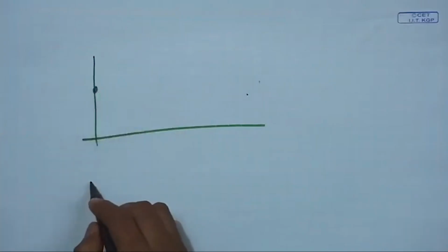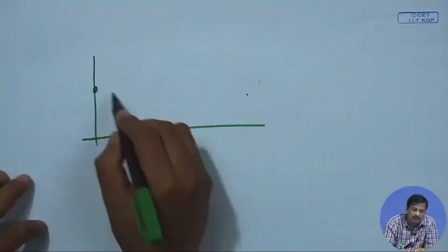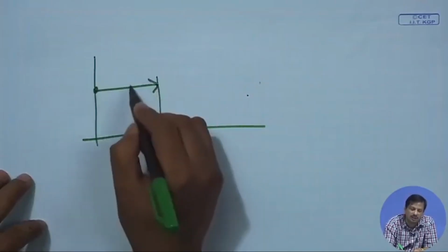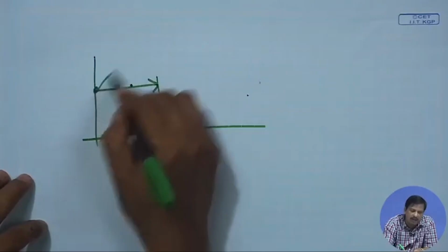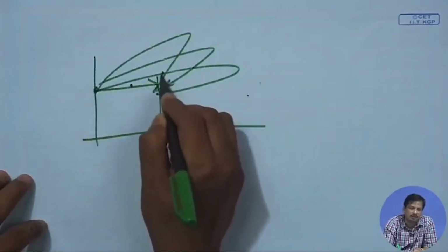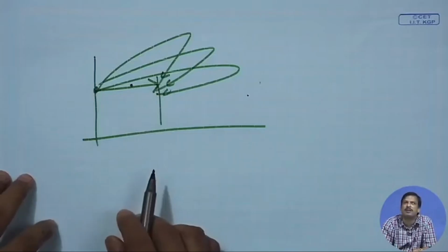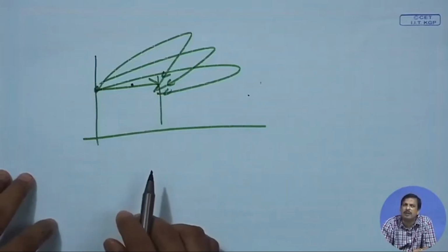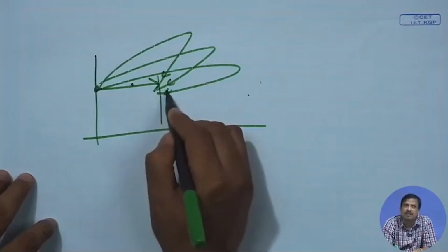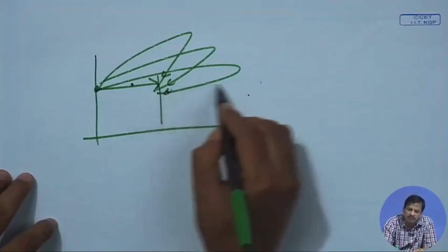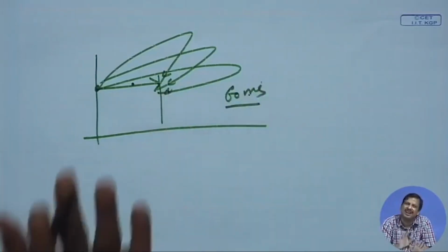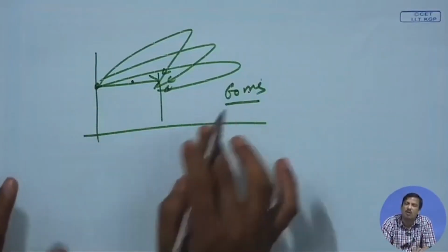I said the texture will be good if the time interval between the reaching of the direct sound and the first 5 or 6 reflections is as minimum as possible. If it is decreased, the texture will be good. It should be within 60 millisecond at least, then we say at least good texture. So, as low as possible.